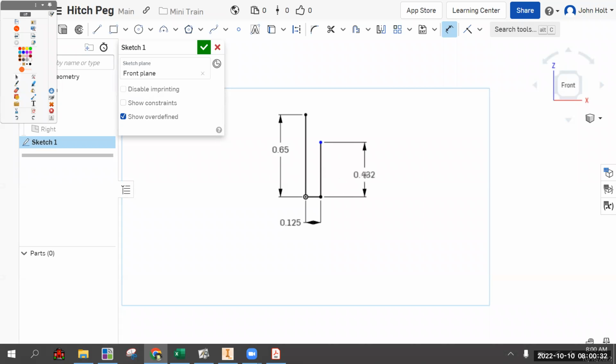Normally, I would just bring out my dimensions away from the center of the part, but because we're going to have some more sketch features over in this area, I'm going to drag this out of the way. The place that you put your dimension lines, extension lines, what have you, doesn't really matter, except that things could get confusing.